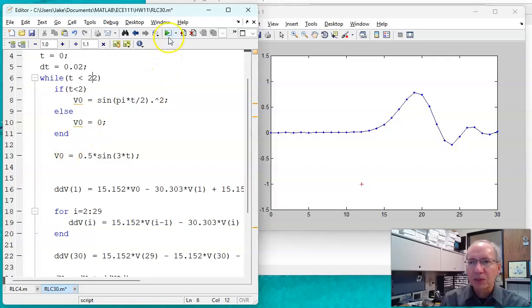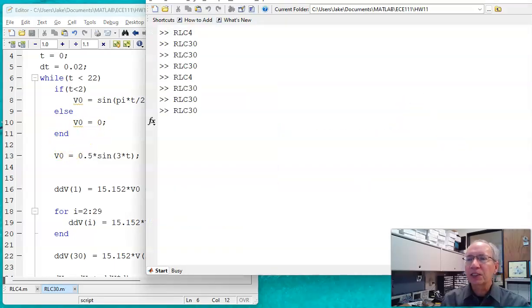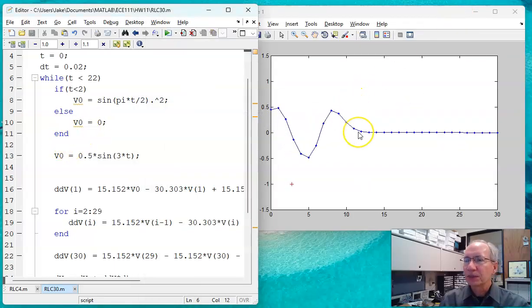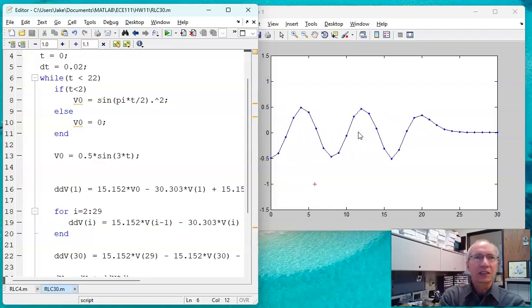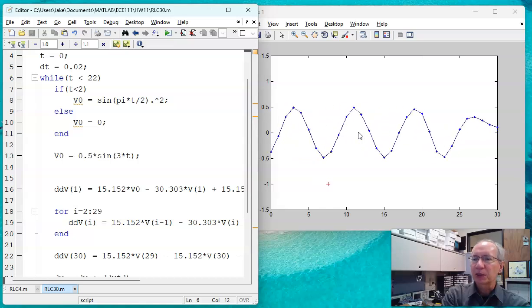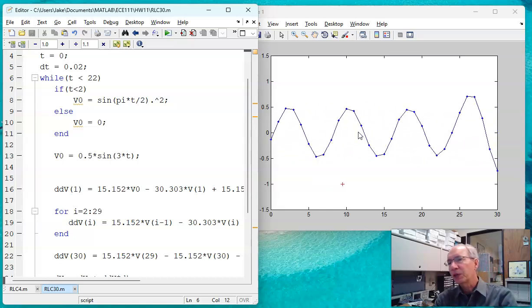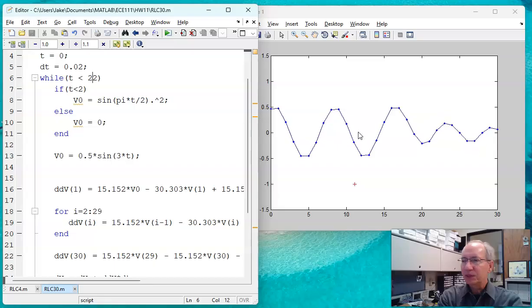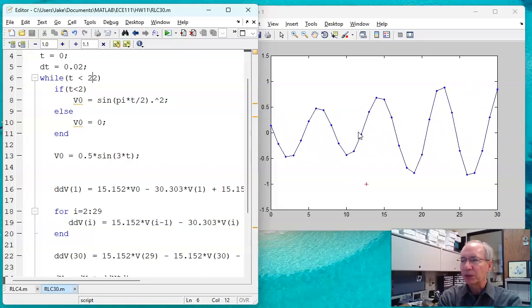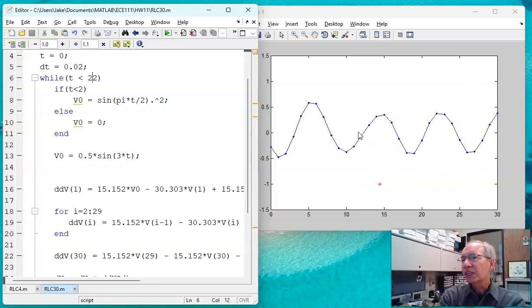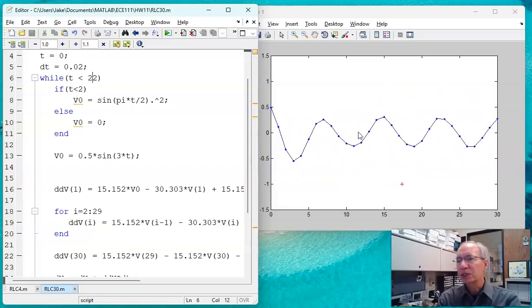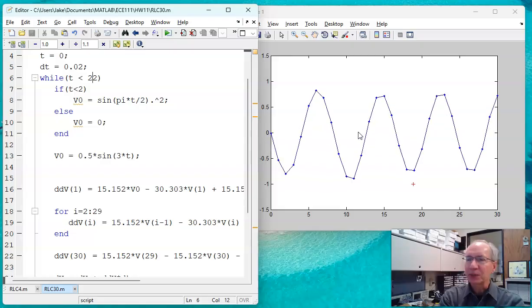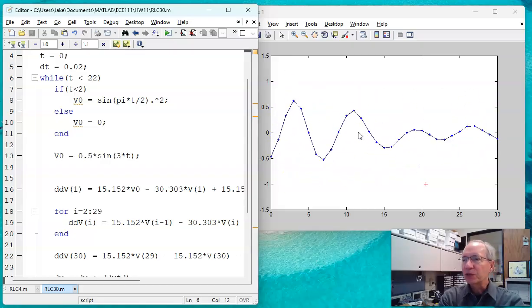22 seconds. When I get plus reflections, I get a thing called standing waves. So suppose this is the wind blowing, this is a bridge, something that satisfies the wave equation, or a circuit board trace where I'm sending sine waves going back and forth. With the reflections, I get these standing waves. That causes bridges to collapse. That causes overvoltage on my circuit, breaking components. Those reflections are bad.